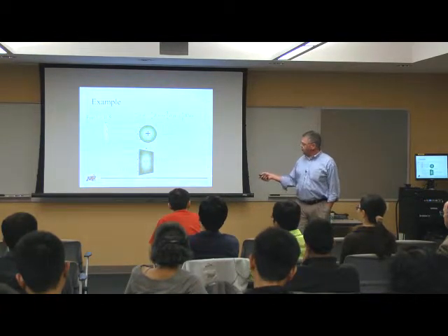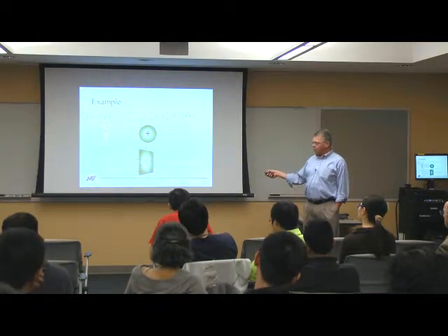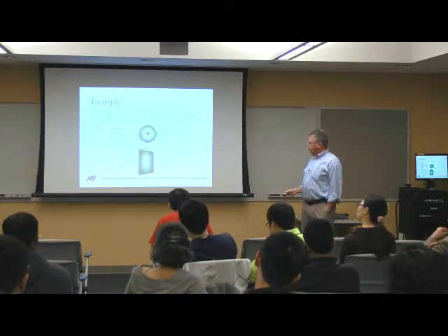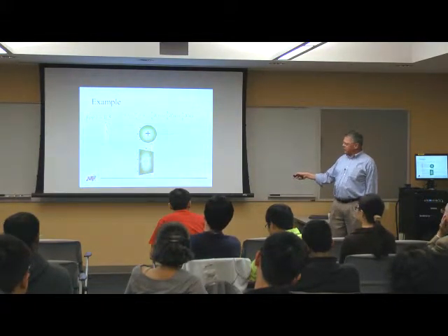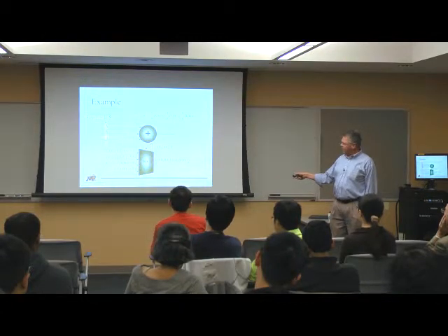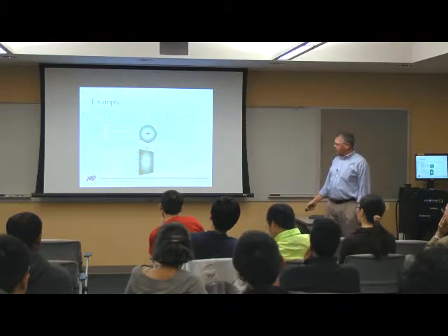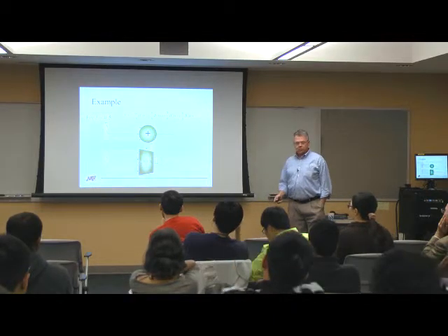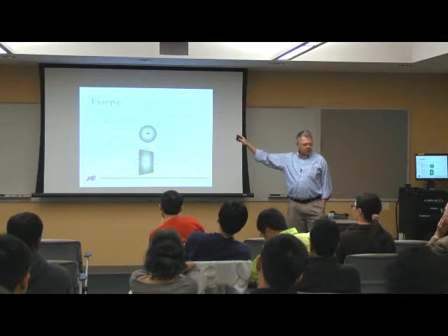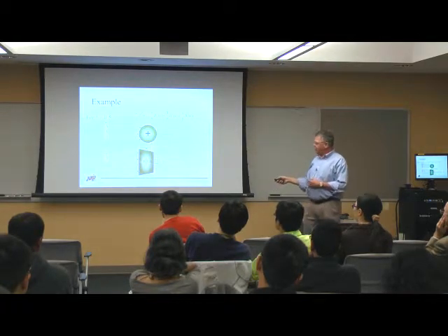So here's my input value. All of these are representing 4/8, but just randomly I got 0, 0, 1 for the first cycle. On the next cycle, this is not truly an adder. It's really just counting the number of ones that are coming into it. So I have 1, 1. That means I have a 1 coming out of here. That means I select that multiplexer input. So I select that 0, and that propagates through to the output. Okay? So all those other values I'm just ignoring because I'm just randomly selecting these, but I'm selecting them weighted by these different coefficient values.